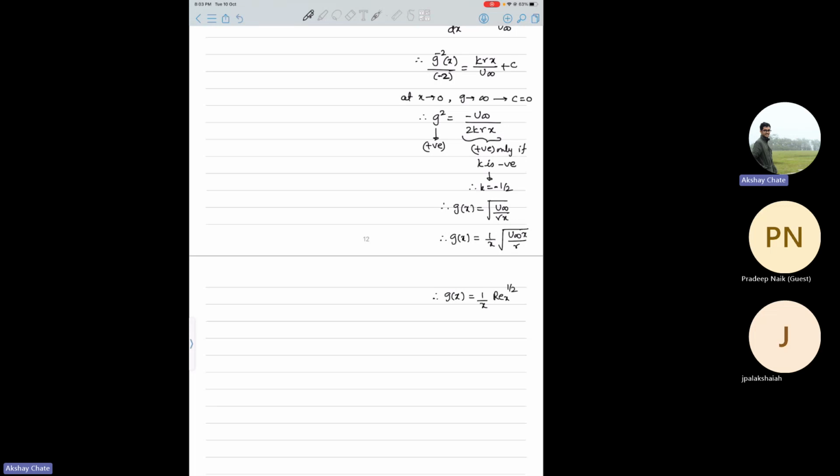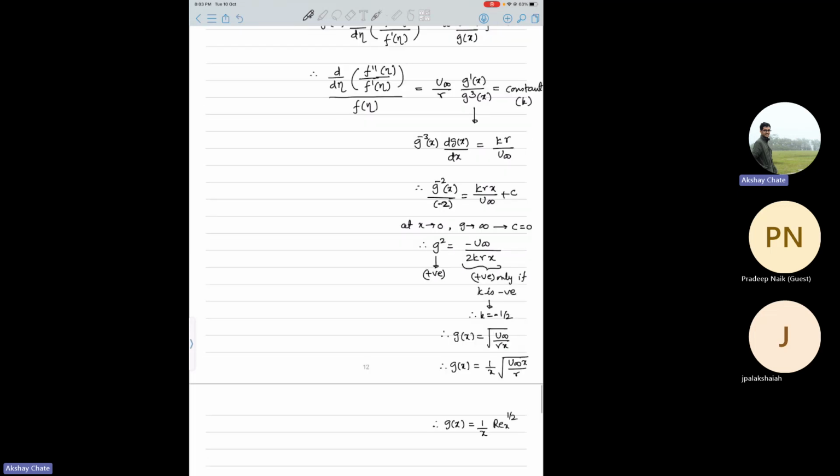So this is some function of Reynolds number. And then the second part, this is actually the difficult one. Here they assume, I mean, this is a standard derivation, okay? I'm not doing anything new, I'm just giving you the nuances of it, because otherwise you won't understand it the first time. So what they do is that they then define some function. This is a process to solve it numerically. So if you don't understand, it's fine, and if you do some calculation, what you get is a third order non-linear equation. So this is also the famous Blasius equation. You don't understand, it's fine, but you should at least remember it's third order and non-linear.